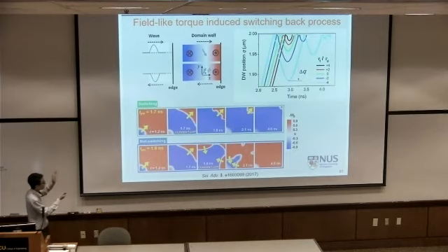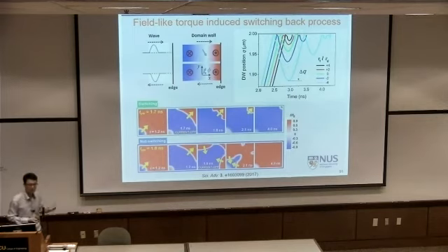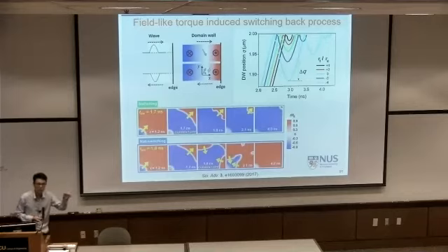So when we switch this, the cobalt iron boron, it propagates, then at the end the domain can be reflected. And when you deflect, basically you change your phase. So basically we have to understand this domain-wall dynamics in a lot of materials, because it's not easy to make a single domain due to the PMA nature. PMA material will give you very small domain size, and in realistic device geometry we will always have domain-wall propagation.